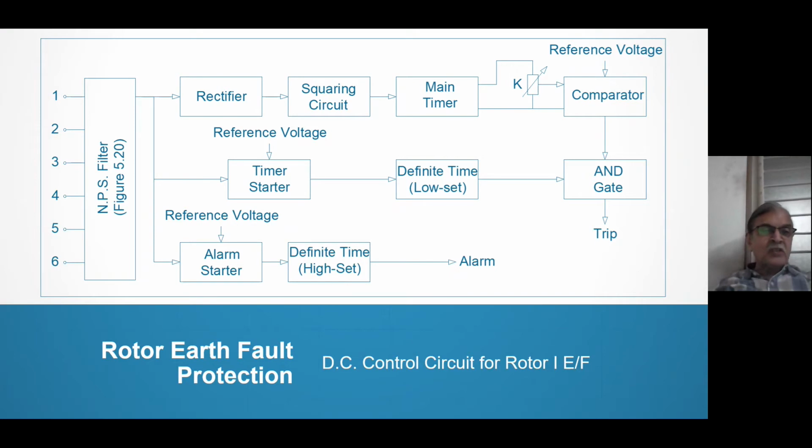First defense is distance protection of the line. Second defense is overcurrent and earth fault protection of the line. Third defense is transformer secondary overcurrent and earth fault. Fourth defense is this. You can see, if an army is fighting, then also there are lines of defenses. So usually the fourth line of defense never has to fight, because the first is fighting.